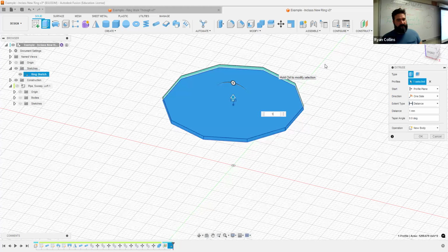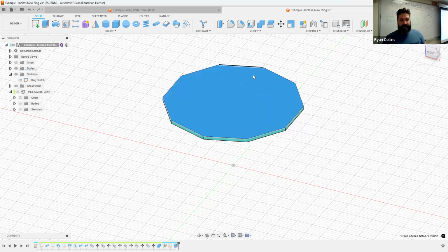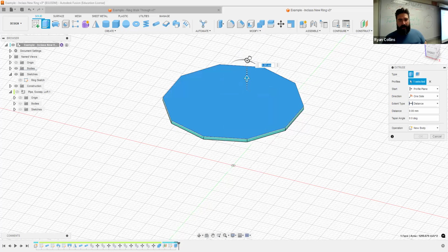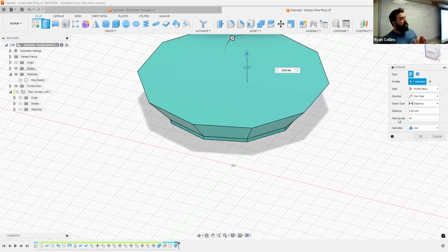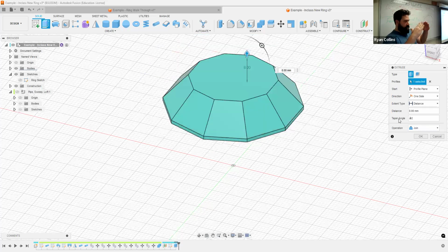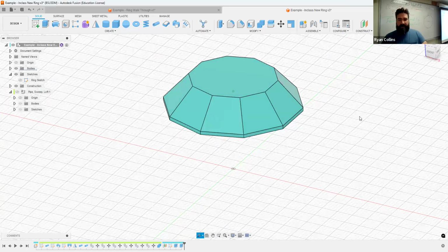From there, we're going to extrude again. From that one, repeat extrude. Now we can go up. Doesn't matter. 8, 10, 300, somewhere in there. 8 works. Now, this is one of the things I was talking about, the taper angle. It does make sense. And when I said 42 degrees is a very common jewel cutting angle, yeah, type that in. Now, 42 immediately goes the wrong way. A positive number goes outward. Toggle back over, put a minus in front of it, and it tapers inward. You can see where we're going with this. Hit OK. Great. Next one, do it again on the bottom.